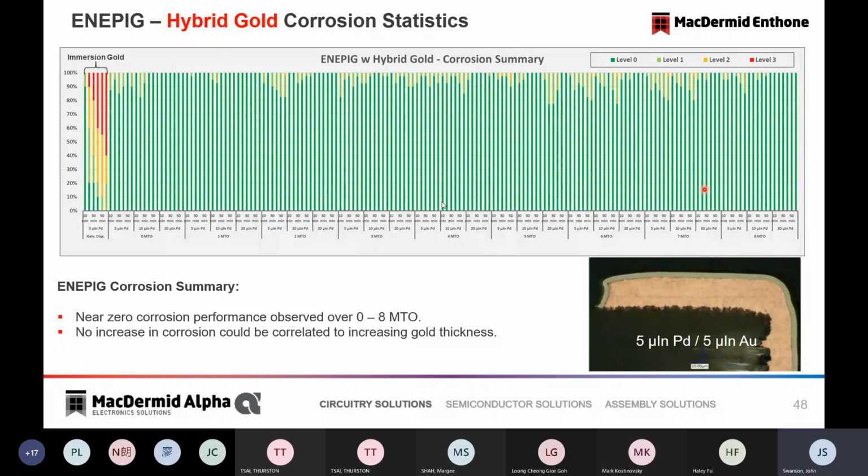You will build up some impurity over time. So this is what happens with electrolysis systems. You build some impurity, and that system is somewhat dynamic. It changes as those reactions occur, and those chemistries must be dumped periodically. But from a nickel perspective, the differentiation has to do with control of the phosphorus. The differentiation also has to do with stabilizers that govern the rate of nickel deposition and its tendency to plate in a controlled way. So your question was not touching on proprietary measures.